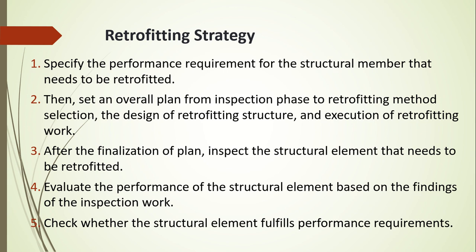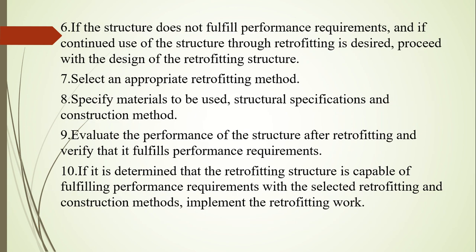After finalizing the plan, we have to inspect the structural element which has to be retrofitted. Then we have to evaluate the performance of the structural element based on the findings of the inspection work. Then check whether the structural element fulfills the performance requirements. If the structure does not fulfill the performance requirement, and if continued use of the structure through retrofitting is desired, proceed with the design of the retrofitting structure.